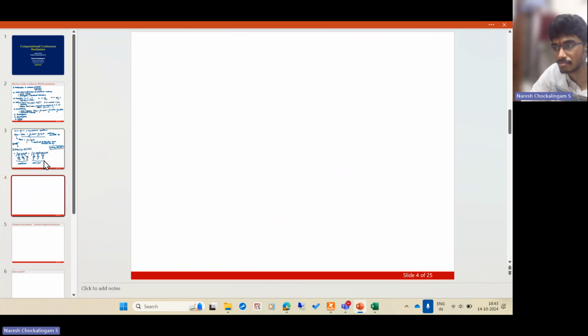Without spending much more time, I can get directly to the discretized system of equations. So the discretization is: we say x is equal to the summation over A going from 1 to n, where n is the number of nodes, of NA of psi times XA. So you express the deformation at any point x as a linear combination of the deformation at some selected points XA. So this is for the deformation.